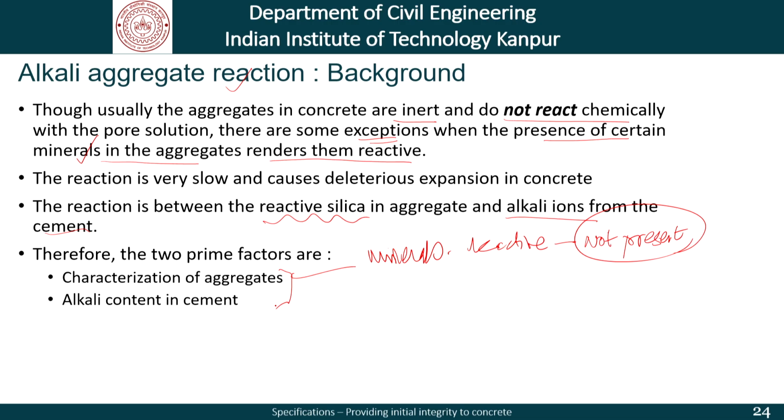It is very important to note that alkali aggregate reaction and the deleterious expansion happens only when water is absorbed by the products of the alkali aggregate reaction.